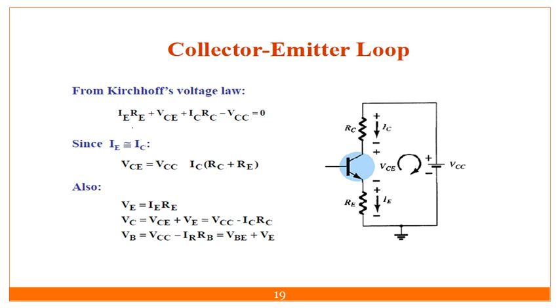So what is there in this case? We have applied KVL and we have obtained the value of VC, which is equal to VCC minus IC times (RC plus RE).